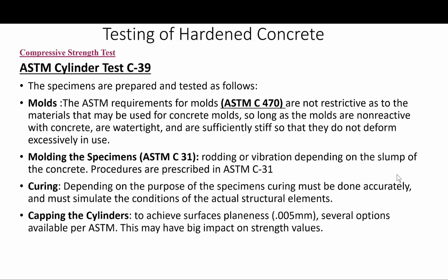The reason for these alternative methods is that poorly compacted cylinders will have lower strength than a properly compacted one. So the method of compaction and following the standards is key. For stiff mixes, which will always be compacted by vibration in the field, rodding simply will not compact the cylinder sufficiently.